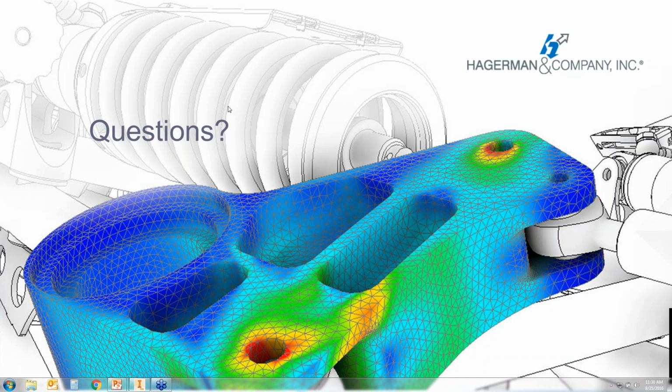That is correct, Mr. Patel. The current tools built within the Inventor software do not provide FEA analysis for the rubber extrusions. That would require Nastran In-CAD, which operates very similarly to Inventor simulation. The process that you've seen is very similar, but it does have the capability to handle those.